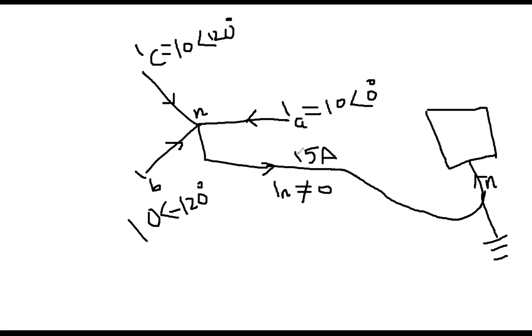For example, the issue is not in this system, the issue is in your system. For example, your system is also three-phase. Just an example: A phase, B phase, C phase, and this is neutral. And your system has been unbalanced. So through the neutral conductor, current will flow, and it might flow in this direction.